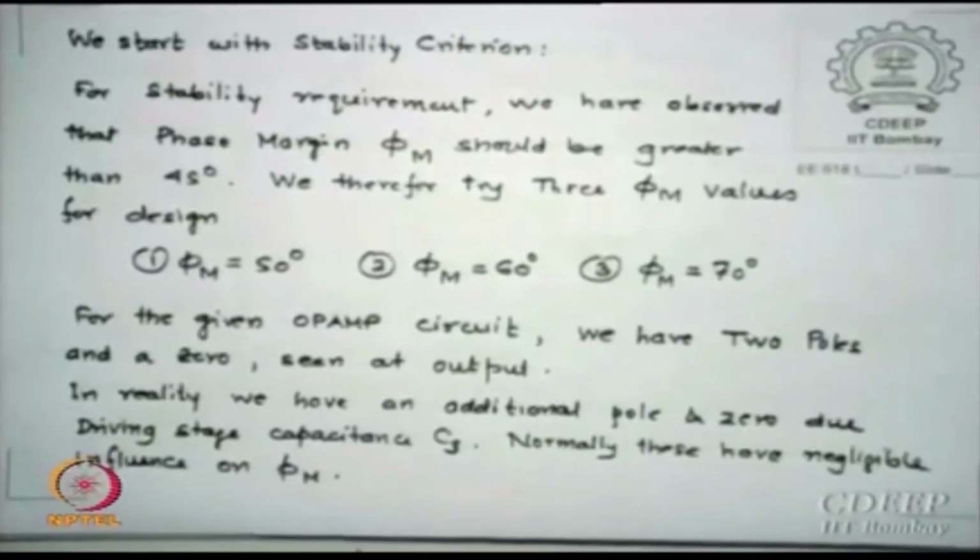So this is the typical range of phi m which I am going to use in design as a spec, as a parameter, is that clear? I can choose 45, 50, 55, 60, 65, 70, any of these values is within my control. I should decide, oh 60 is good enough for me. If you say no, I want minimum 65, you take 65.